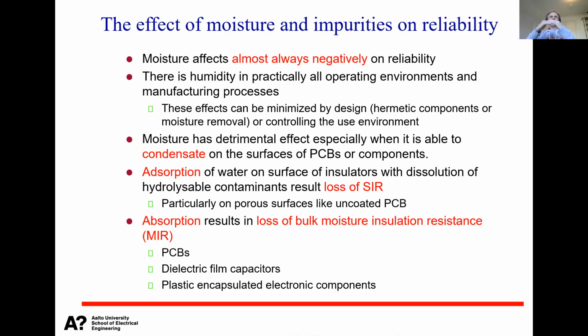Adsorption means that you only have the water molecules at the surface, which means that your surface insulation resistance is decreased, but it does not have any other effects, like affecting the mechanical strength of the product. It just decreases the electrical performance of the surface. That can of course be very harmful, but it does not have this kind of long-term effects.